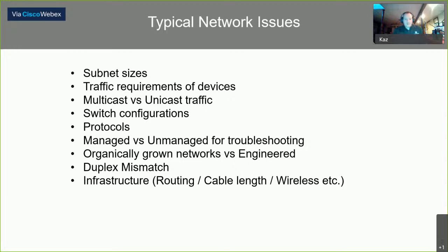And another thing is infrastructure. So not paying attention to cable bend radiuses, using zip ties and really ratcheting down on a cable and compromising the noise characteristics of the cable. Routing, putting your Cat5 or Cat5e or Cat6 in the same cable tray where you've got the VFD talking to its drive in that same cable tray. Cable length, 150, 175 meter cables that are going along that should only be 100 meters. Wireless, people putting in their own wireless infrastructure without doing a site survey, so they're stomping on other channels.